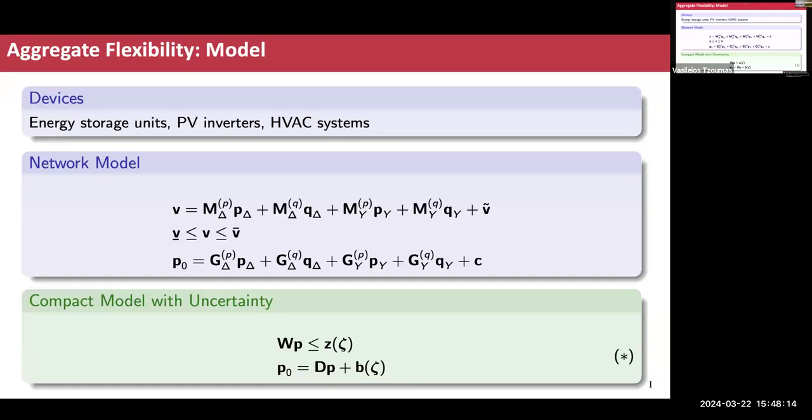In this case, we're using a linearized power flow model, which, as we can see from the first equation here, relates the real and reactive power generated at each device to the voltage. So the voltage and the power output have a linear relationship here. This is commonly used for distribution system modeling. It's a variant of the LinDistFlow model that is widely used in distribution system analysis.